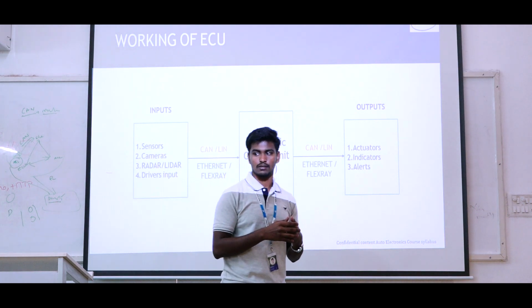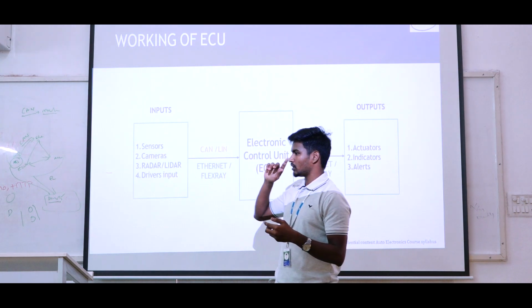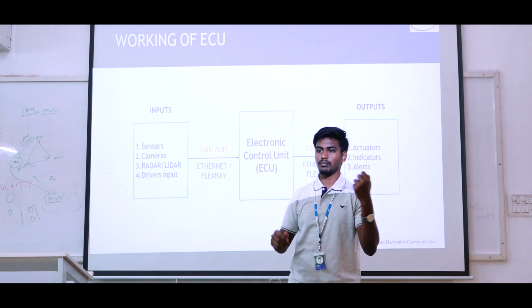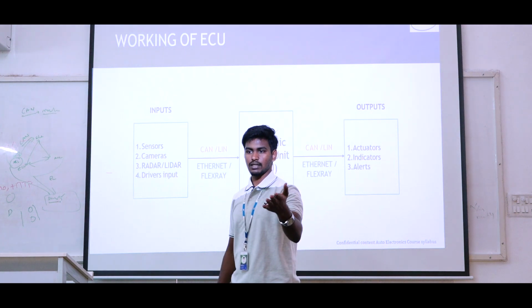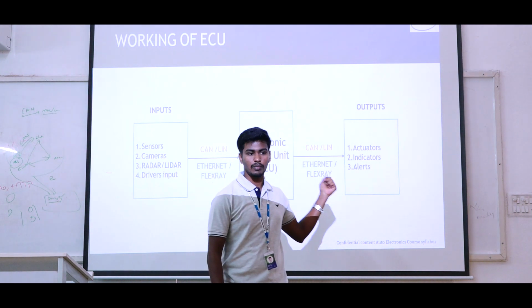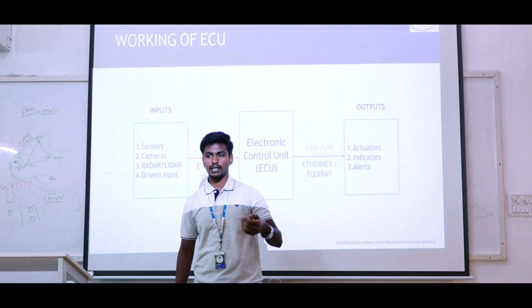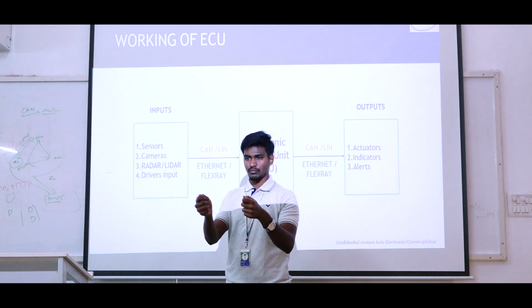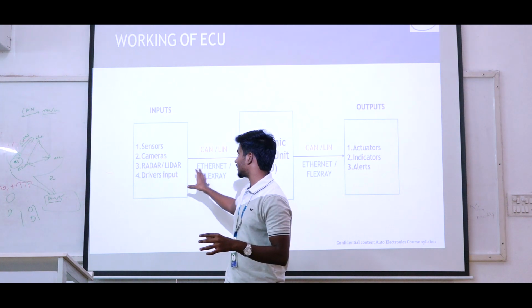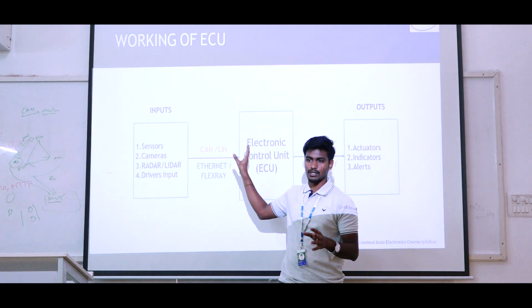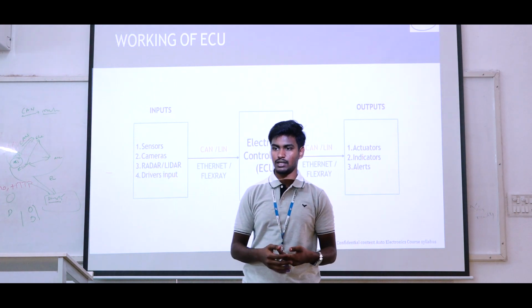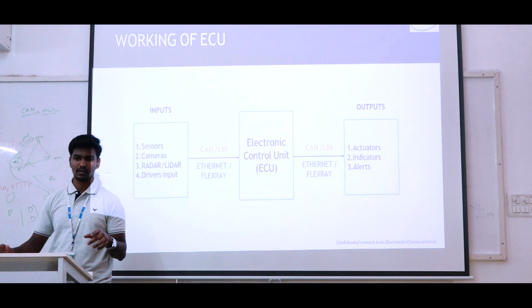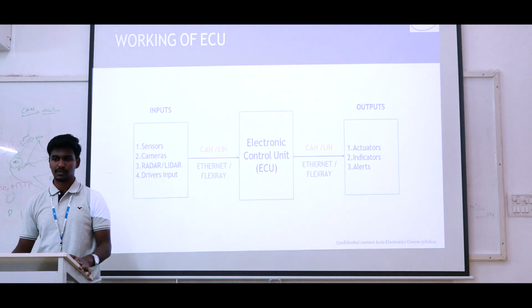So, unified diagnostic services (UDS). For example, if you are enabling the reverse gear but at that time you are not getting camera detection of any people, that is the error. Whenever we send the vehicle to the garage, they will check with the diagnostic services, and we directly get that error detection. If it is a wiring problem, they just check with meters, or if it is a problem in the data transmission or the ECU, they reprogram and do ECU flashing. So based on that, the errors are handled. In the UDS section we have some 27 services. I will explain what they are.